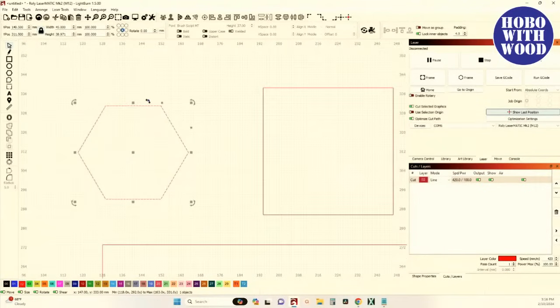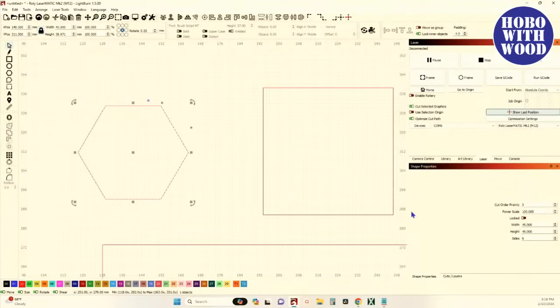Well, used to, if you wanted to change the sides in your shapes, you'd have to go to your shape property tool down here, and tell it how many sides you want on each polygon you've created. Well, now this mysterious little blue dot will do just that. As you drag it left or right, you change the number of sides on your polygon, and that's cool.